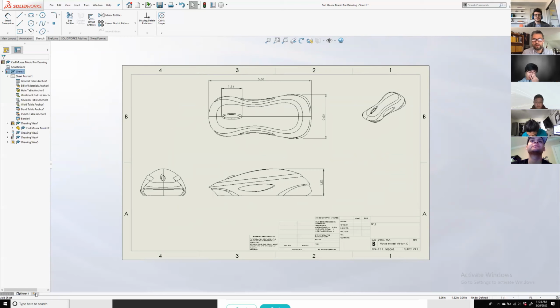Are there any differences? So it's not necessarily that you have to show 3 views or you have to show 5 views. Sometimes there's no top view. Like if it's a cylindrical item, you might just show the width as a circumference, and it might just be a top view and a front view. And if it's cylindrical, you won't show a right view. It might just be 2 views. Okay, great. Hopefully that answers your question.